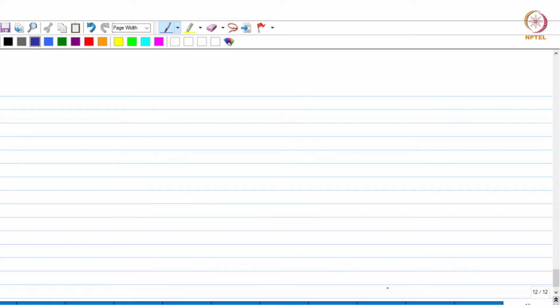These alloys can be easily formed into complex shapes, and extrusion is a very commonly used process for shaping such alloys. And their quench sensitivity is also low, and therefore they can be directly quenched from the extrusion temperature.